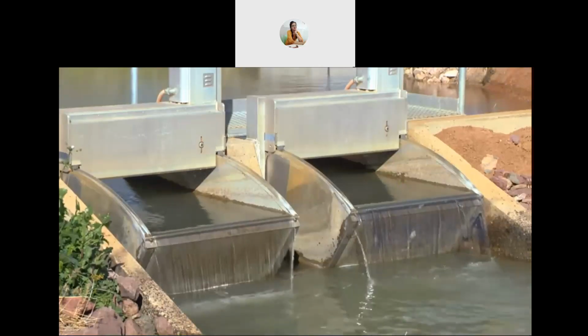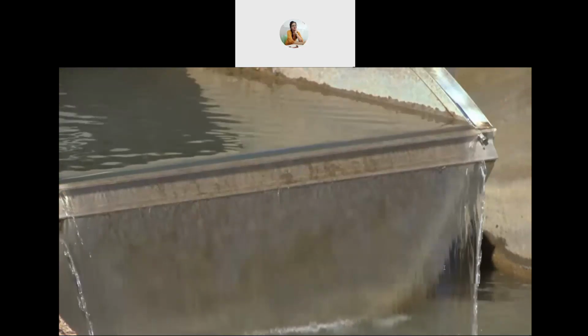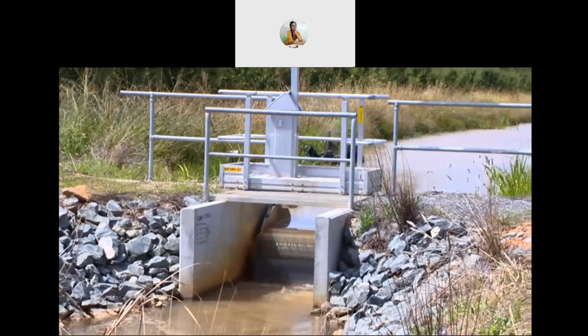It means that you can get precision control of flows throughout the irrigation system, and that all those flows are completely automated. If a farmer wants to order water, they either do it over the web or over the phone. They can put their order in, the system automatically checks whether they've got enough water in their account. If they have, it starts the outlet at the time and at the flow rate they want, and all that process doesn't touch again, and we're not involved in that at all. It's all done automatically. So the 2 hours still blows people away. The fact that a farmer can order water with 2 hours notice, and if it's an emergency, even quicker than that.